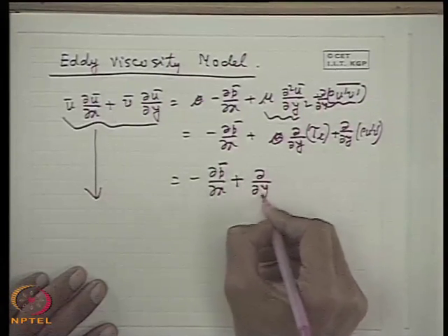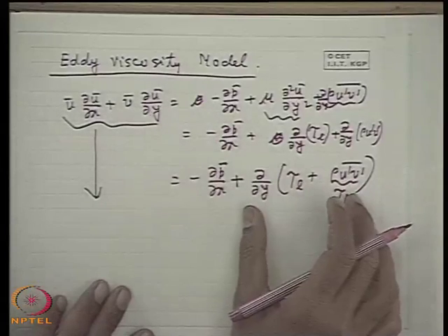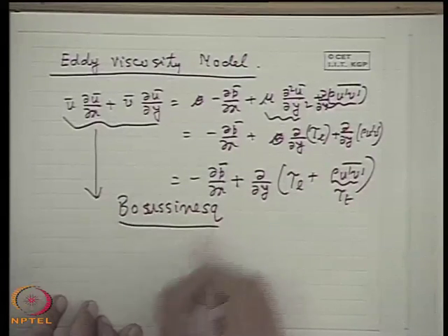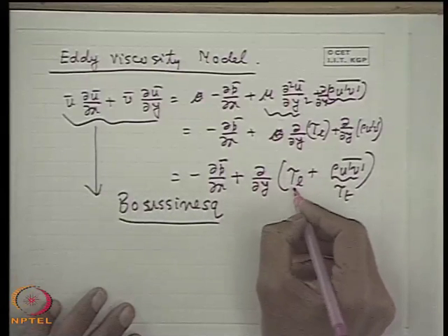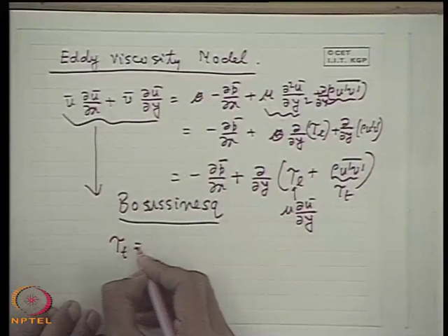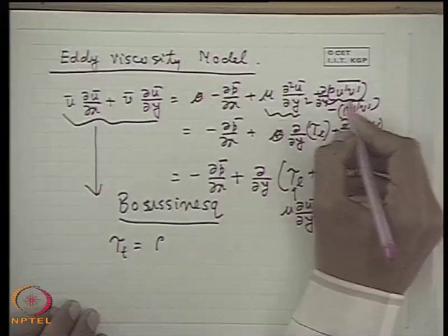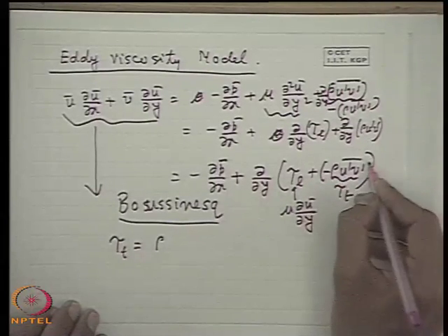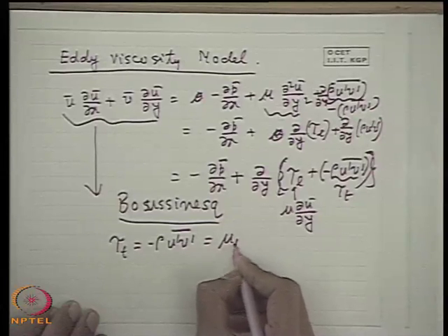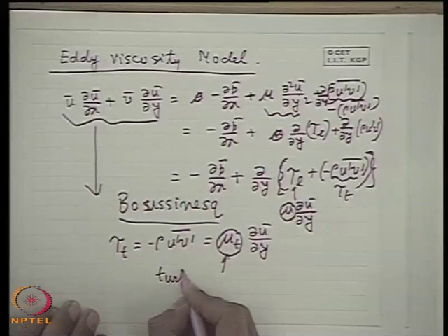But what is the difference? Along with the laminar stress, we come to a turbulent stress, tau t. How to relate that? In a simple case, I just explained how to relate that. So, it was Boussinesq first, Boussinesq is a great scientist, who first proposed, why not, tau L is mu ∂ū/∂y. So, similarly, we define a turbulent viscosity, which relates tau t is equal to, it is a minus sign, I am sorry, minus rho u' v' bar, it will be a minus sign there. So, that minus rho u' v' bar should be related with the mean velocity gradient through a similar term like laminar viscosity, a term mu t, which is known as turbulent viscosity.